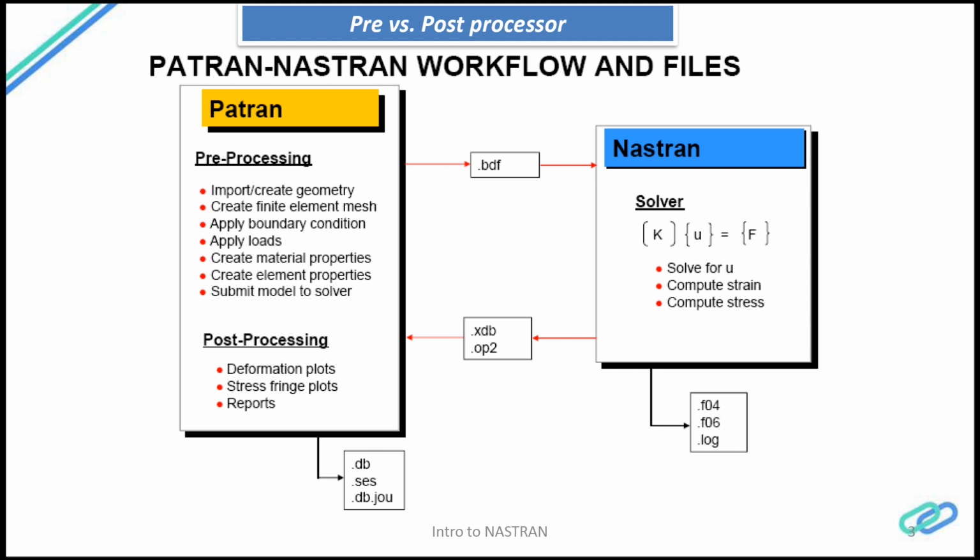We also call it command format, or NASTRAN cards simply, which is a text editable file with the extension .bdf. This will be submitted to the NASTRAN solver. This solver will solve this file, which is your model, and then it generates the output.